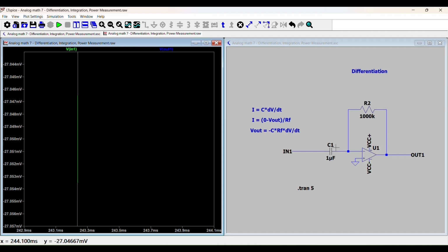And in real life, the reason why that doesn't happen is because, first of all, capacitors have an equivalent series resistance, right? And because they have an equivalent series resistance, now you cannot have an infinite current across them. So there's an inherent current limiter in series with the capacitor.